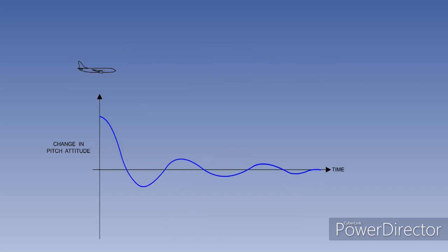Short-period motion consists of rapid pitch oscillations, during which the aeroplane is constantly restored towards equilibrium by its static stability and the displacement being decreased by pitch damping. So flying at high altitude will tend to reduce dynamic stability due to the reduction in aerodynamic damping. Short-period oscillation involves rapid and significant changes in angle of attack, load factor, so can generate damaging flight loads to the aircraft structure.